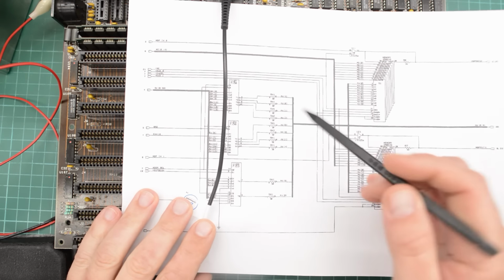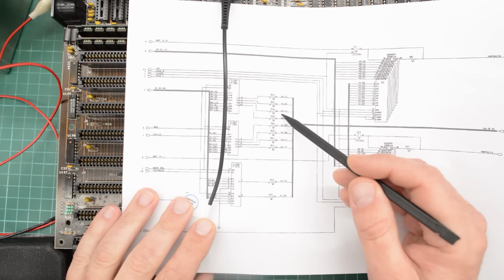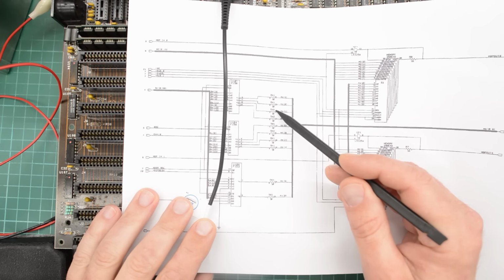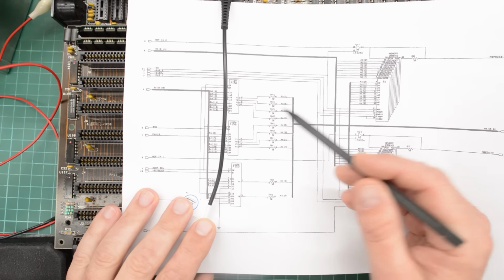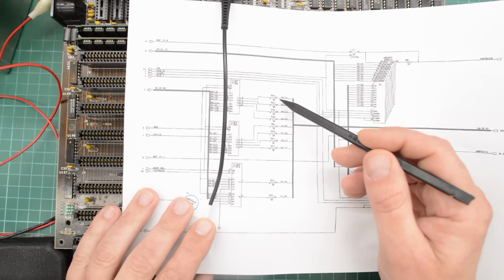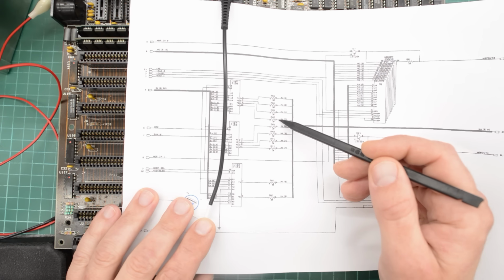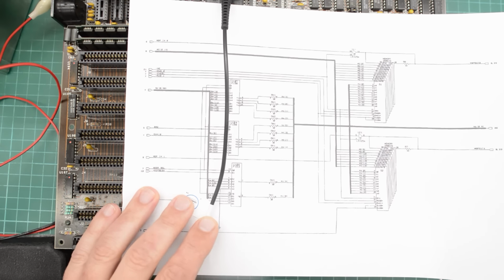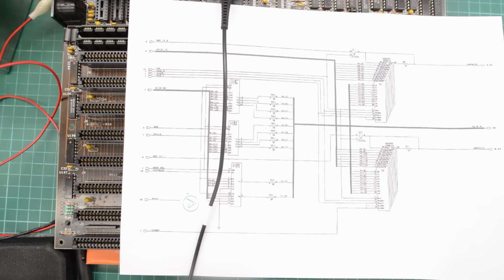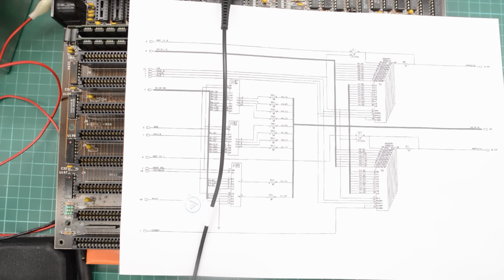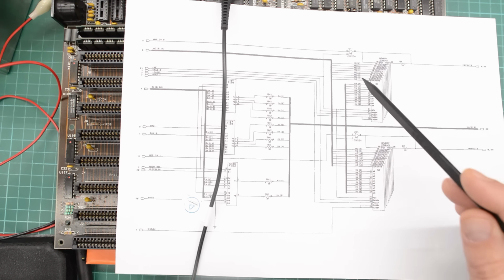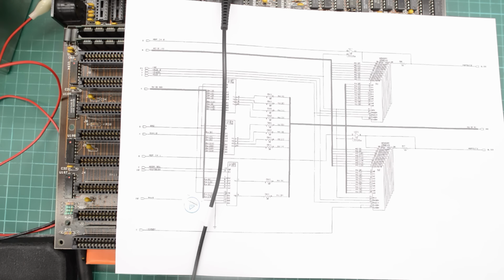So if we look at the schematics here, yeah, I can't really read if that is AN1 or AN2. Unfortunately, I can't read the pin numbers here. The scan just isn't good enough. So that's not very helpful. The only thing that told us is that we have a good signal on some of the pins. But we don't know if all the address lines are good or not.